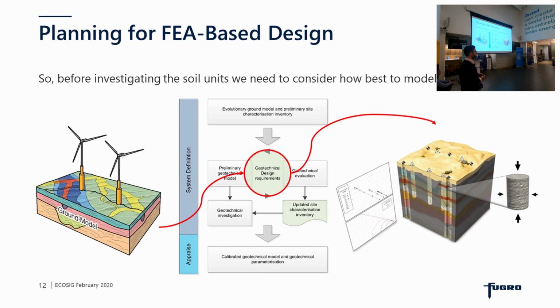Otherwise, you end up in a situation where you hand over a soil data set to a designer and ask them to run very complex finite element analysis, but actually you haven't given them any of the data they need to parameterize the model. And then you end up in a situation where that designer needs to make significant assumptions regarding the parameters and assumptions regarding the soil response model, and that ultimately will be handled with conservatism in the design, but potentially those assumptions could be non-conservative if the right response measurements aren't made. So the earlier that we can get those response measurements or an idea of how we're going to model soils into our overall project life cycle, the better the outcomes will be for foundation design.